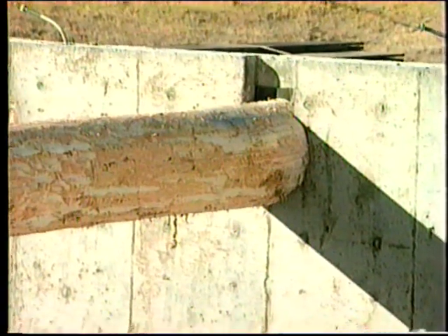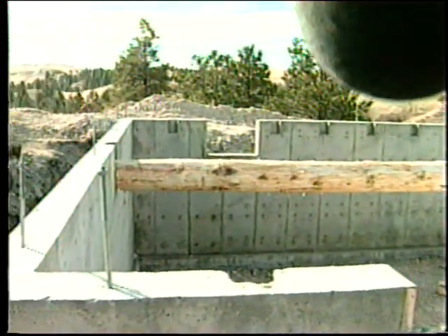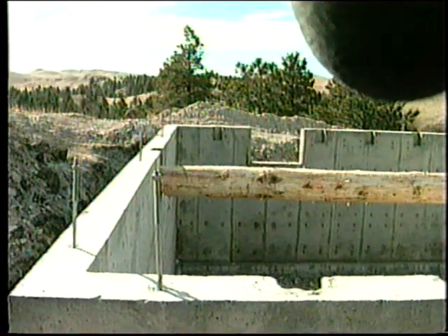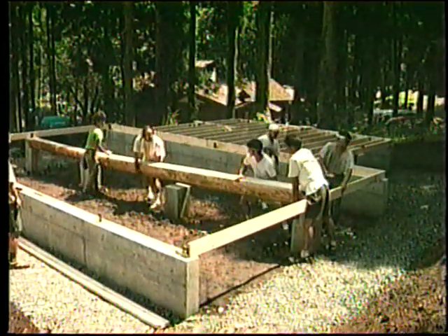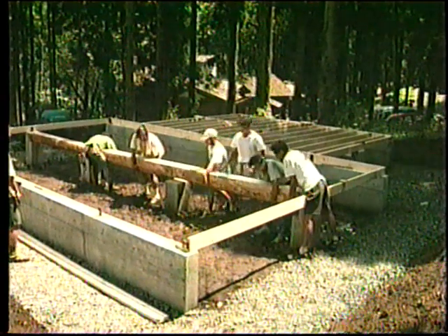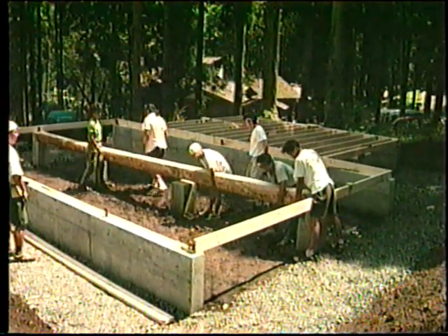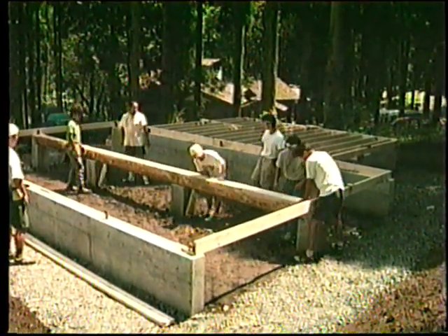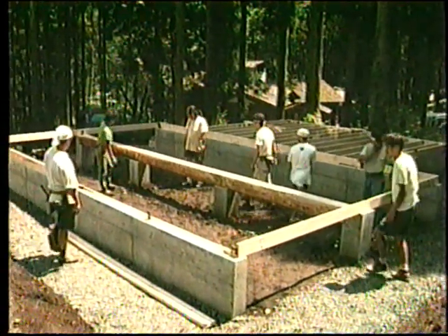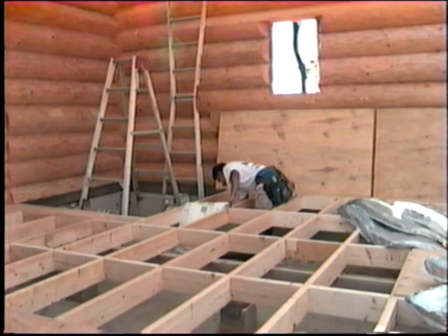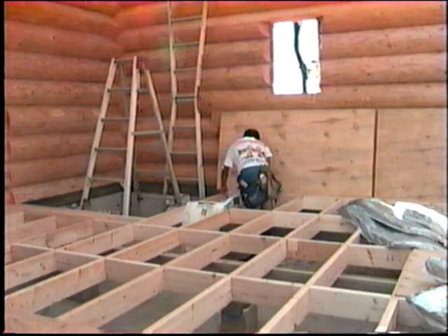Beams and joists are very much the same thing, and the terms may be interchanged in some books. A beam is more often considered to be a heavier timber that will carry an intermediate point along the floor joist. This provides for larger clear span. A joist is a lighter timber with closer spacing.